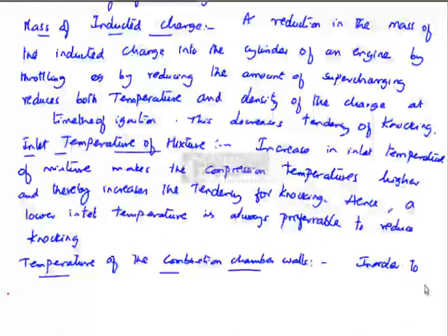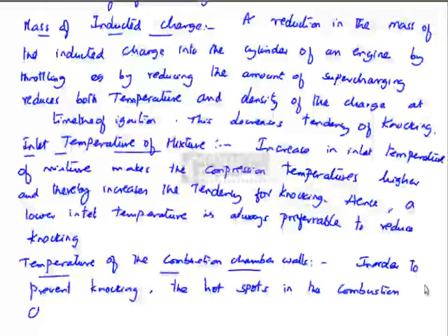In order to prevent knocking, the hot spots in the combustion chamber should be avoided. That means the combustion chamber walls must be properly cooled.